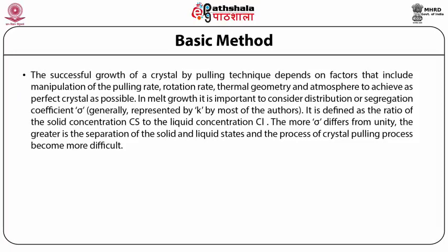The successful growth of a crystal by pulling technique depends on factors that include manipulation of the pulling rate, rotation rate, thermal geometry, and atmosphere to achieve as perfect a crystal as possible.